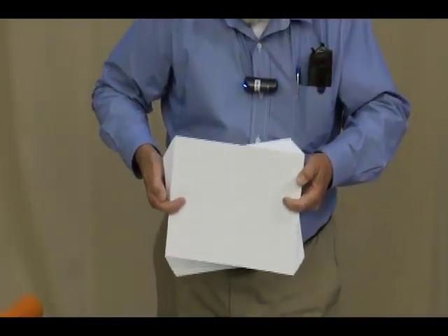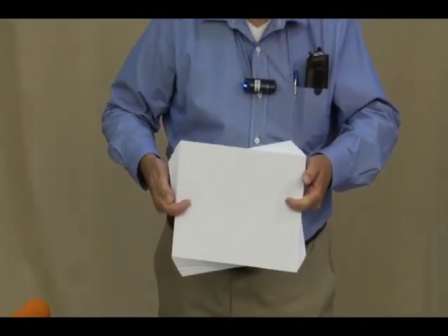So I've applied what amounts to a torque to that system, and you can see the sheets of paper have slipped on one another. And you can also see that at the center of the rotation, which is in the middle of the rectangle, there has not been any significant slip, which is why the torsional shear is 0 at the center, and it's maximal at the outside. Let's go back to our slides and we can see some other demonstrations of this.